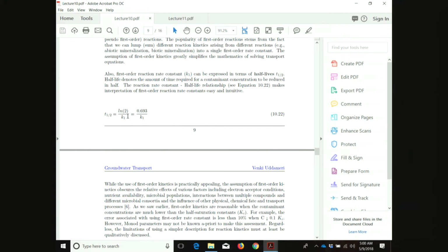because you have much smaller pore space, much less mixing. So if you do an experiment in a CFSTR or a batch reactor, your conditions are a lot more ideal than in the subsurface. If I were to do these experiments in the subsurface, the reaction rates will be much lower. In other words, if you take batch reactor data and put it into your model, you will overestimate degradation. If you overestimate degradation, you will underestimate concentrations, which is a bad thing.